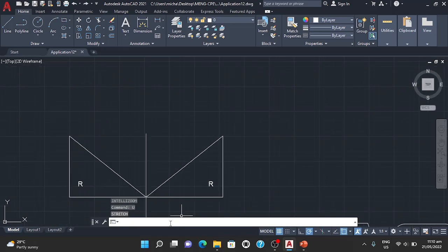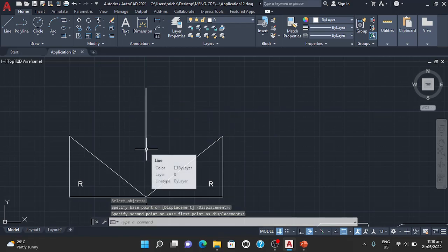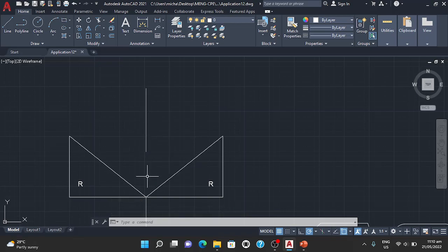Undo. Okay. So in stretch, as you can see, if we type stretch, select the object, enter, select the first point or the end point here, select the second point. So as you can see, the displacement of this stretch line is a move. So let's undo it. So the best way to do stretch is to click the line. Okay. Click a certain object, which is the line.